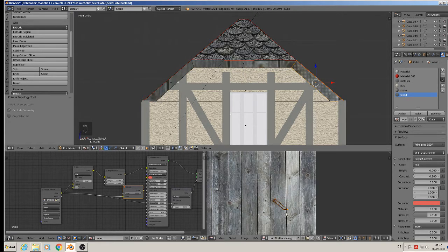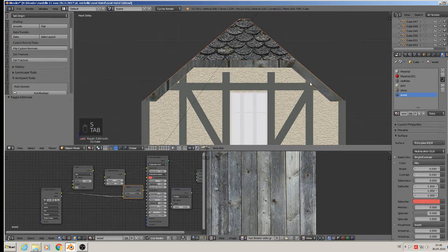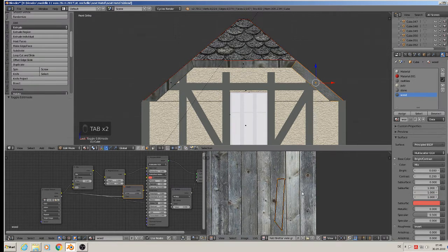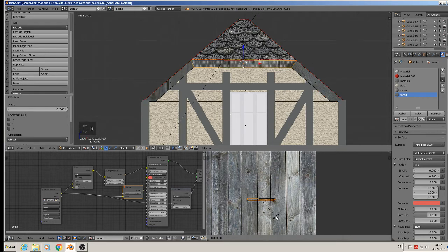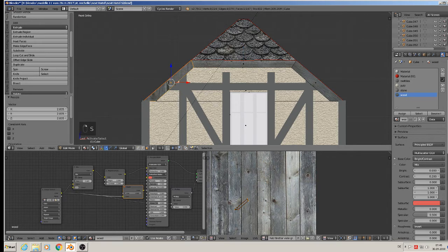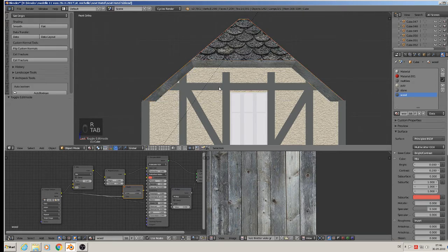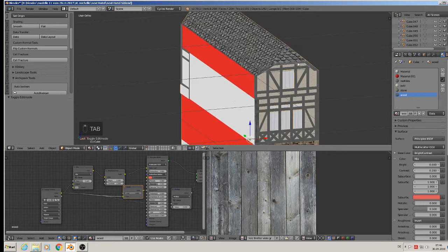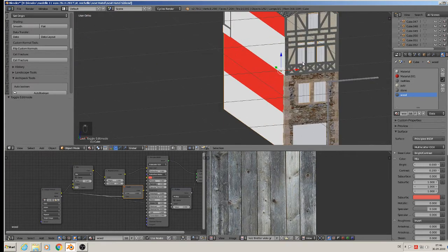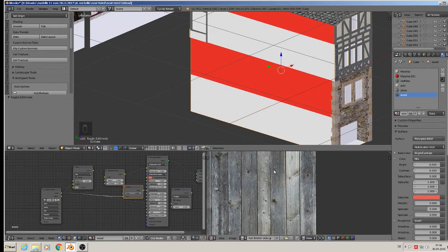So when we get that, we can rotate it, and then it follows the wood structure there. Here too, we rotate 90 degrees and scale them up, and we have nice wood there. Here too, rotate, scale up, grab it, position it, rotate it. So we have to do that with all these wooden parts. We have to bring them here to fit.